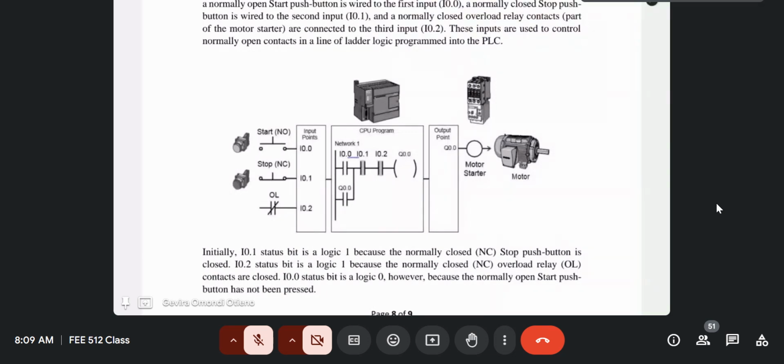So you expect that when you press a button, the machine is going to stop. Now let us look at it logically. If this was a normally closed contact, let's just have one normally closed contact. So we have a switch somewhere. You've got a switch, which is normally closed. So that's a normally closed contact. And then upstream, it is connected to a normally closed contact. Because we were saying, what if we decide to make this a normally closed contact and that a normally closed contact? So now, remember, this is already at logic 1 because it's closed.